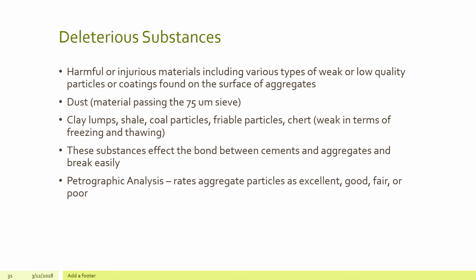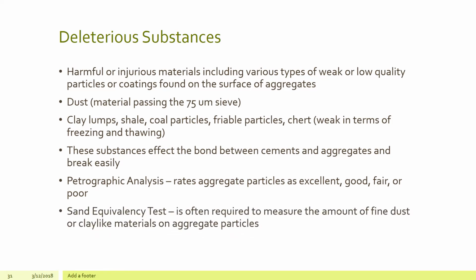Petrographic analysis rates aggregate particles as excellent, good, fair, or poor. A sand equivalency test is often required to measure the amount of fine dust or clay-like materials on aggregate particles that we have.